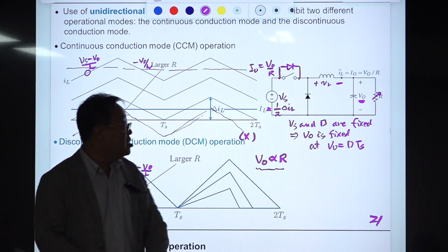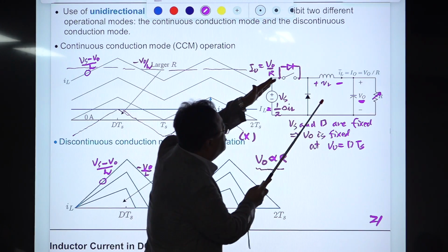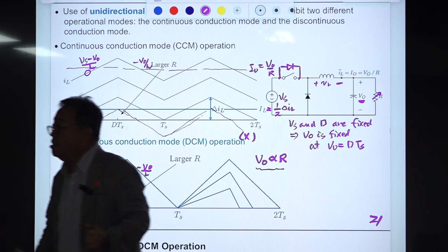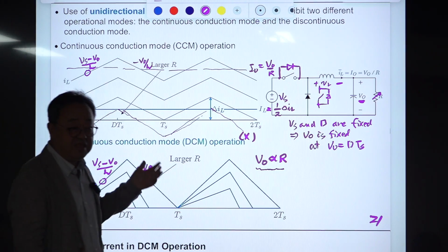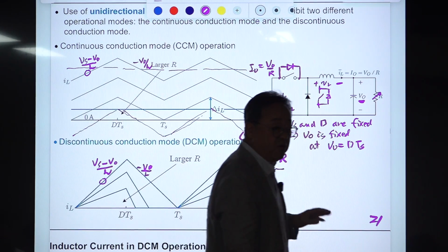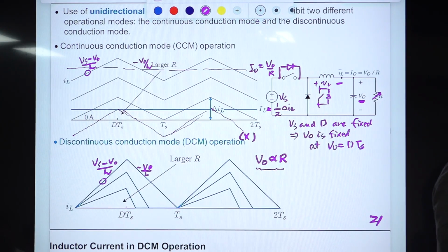So if you use two MOSFET switches, they work in a complementary manner. So they call it a synchronous buck converter. But they are not really synchronized, they are asynchronized. Complementary fashion, maybe asynchronized reactive buck, but they call it just synchronized. There is just some timing exchange between them, so they call it synchronized buck.